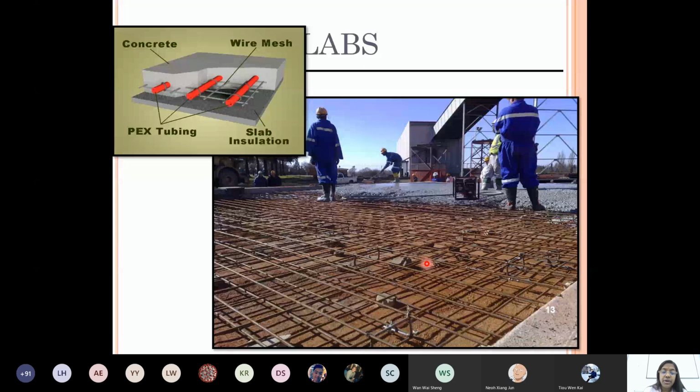Because of these covers, it will fill up the concrete. So after setting everything, if you remove the cover and the formwork, the concrete will be there over the reinforcement to the thickness of the cover, closing the reinforcement and keeping it in good shape and complete.